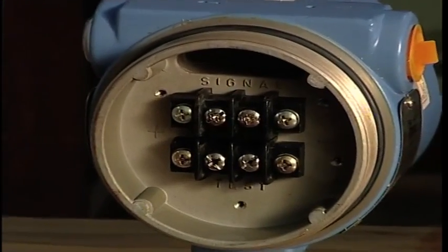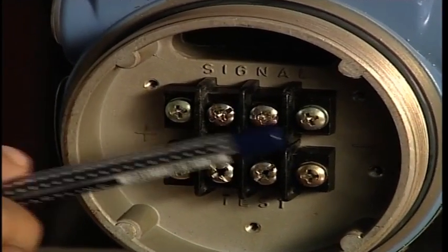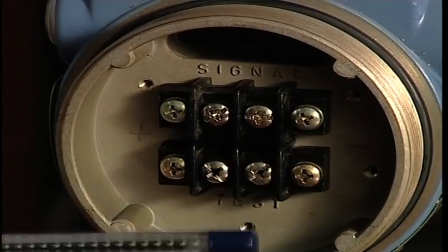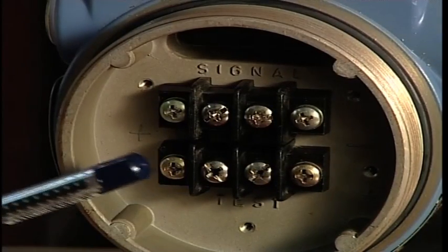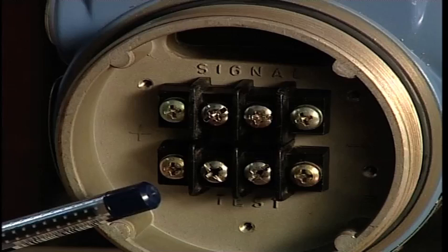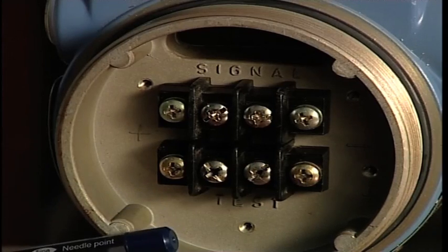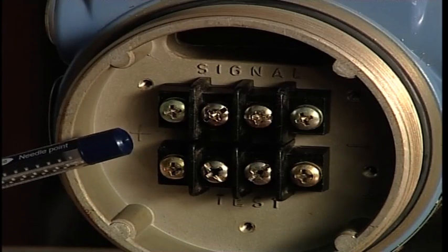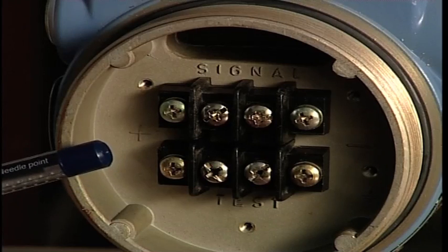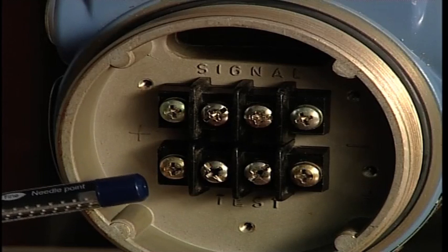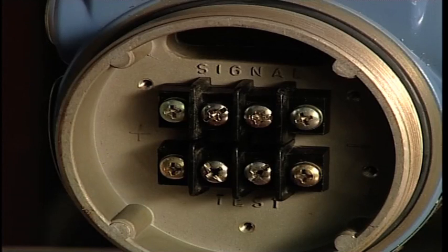You see here that we have positive signals, because in the process the output is 4 to 20 milliampere and the supply voltage maximum is 45 volt DC, because in all processes, as you know, you cannot give a much higher supply voltage. That is also not necessary, and it will give output according to the variations.